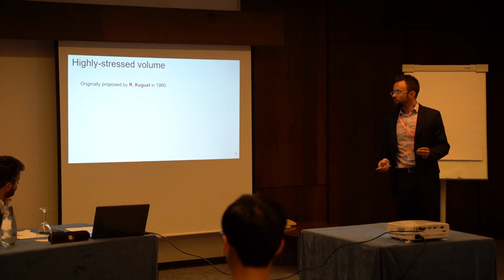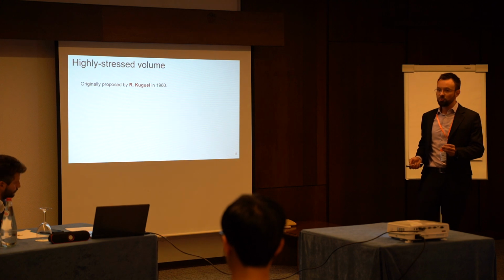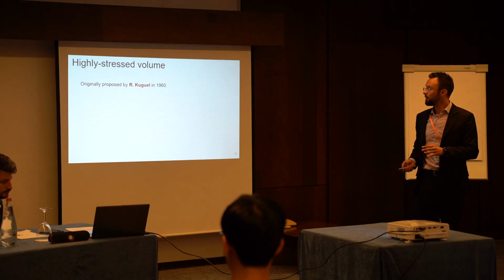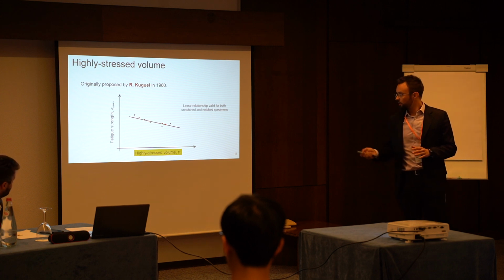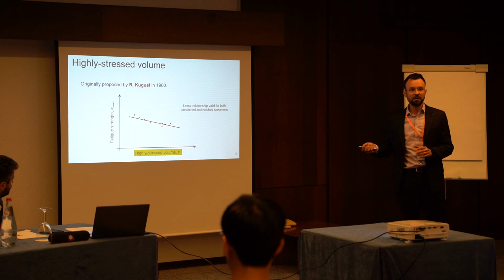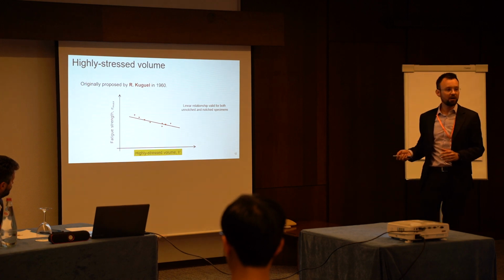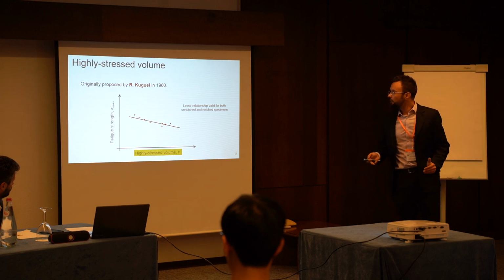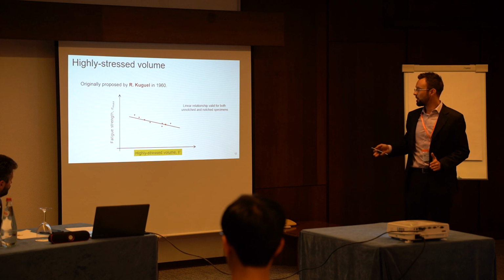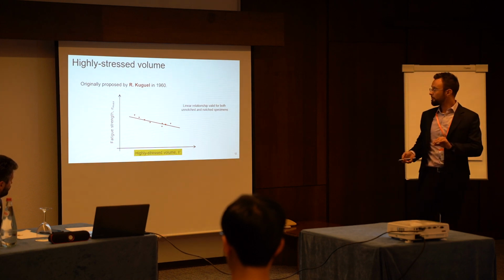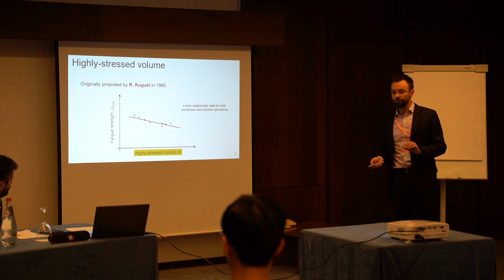This concept, highly stressed volume, was originally proposed by Papuga in 1960. He found interesting results: the fatigue strength decreases as the highly stressed volume increases. We can see an interesting linear relationship in a log-log scale for both smooth and notched specimens.